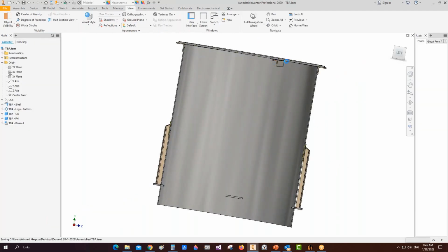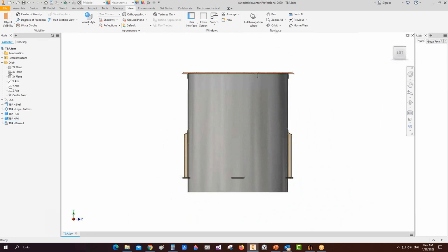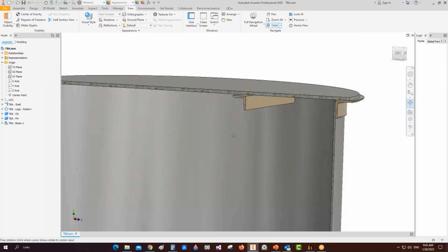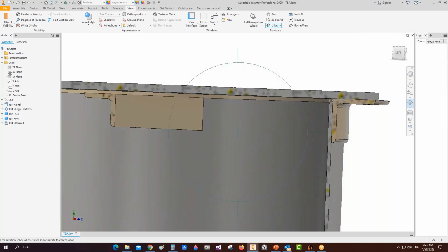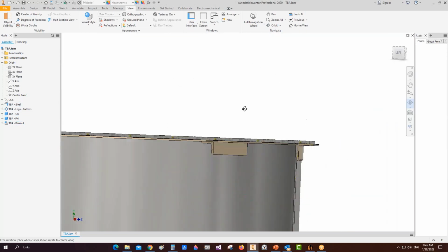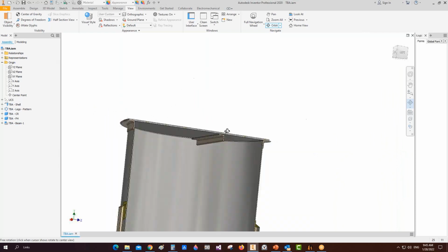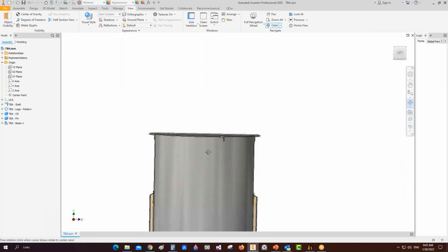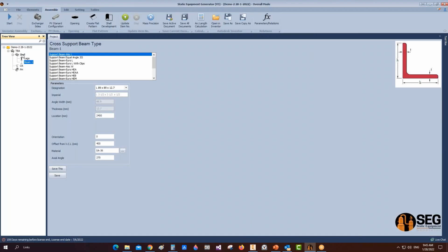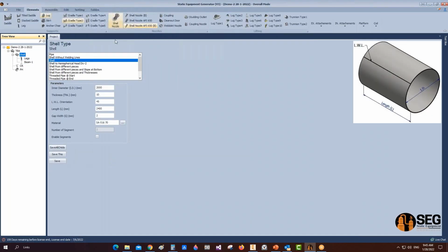So by that way you can add the bracing like that for the compression rings, and we need to increase the location by 10 millimeters here. And by the same way, you can add another stiffening beams inside the shell to be welded to the head like that. And if you would like to add a blind flange, we select the shell, for example,